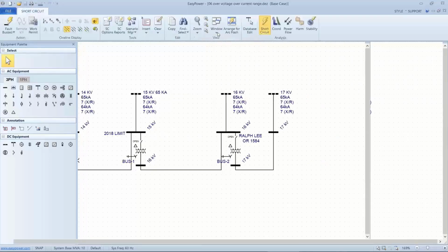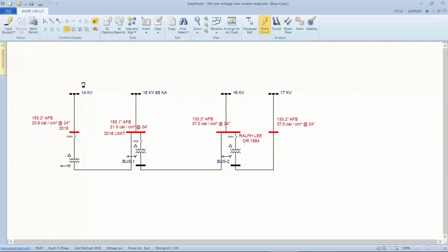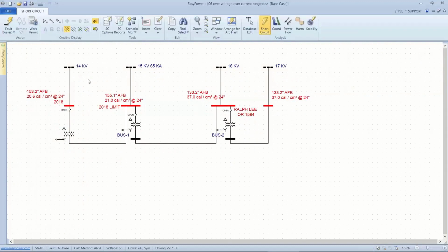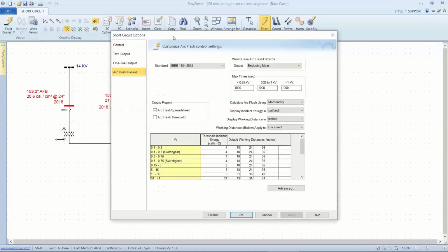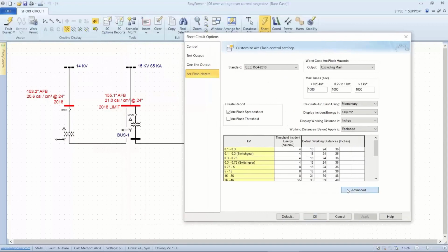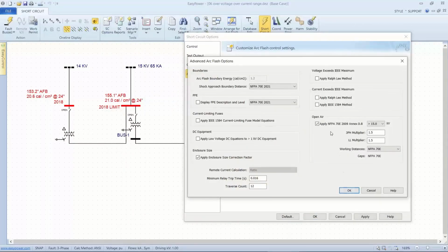So let's see what our short circuit results are. And again, it's more the methodology that I'm emphasizing here, not the results. So we see a modest increase when we get a 10% difference in voltage below the limit, and although it's higher, we have a modest difference between the 20% and the 10%. And so if we look at how this has been calculated, right now I'm comparing this to the annex single line to ground.